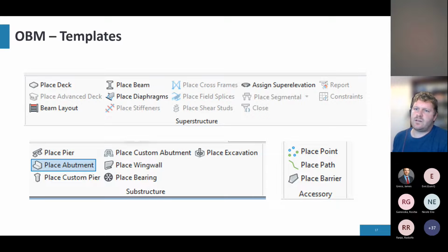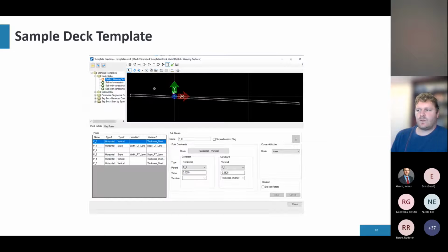So the libraries are all made up of templates. Again, what I just touched on was editing and creating custom templates that way. Say you don't have a new PennDOT barrier in your library, you can pull that out, create it, save it as a template, and export that as an XML file and place it in your workspace. And then it's there for all users to then apply to whatever bridge they want to, or to open it up as they check your model.